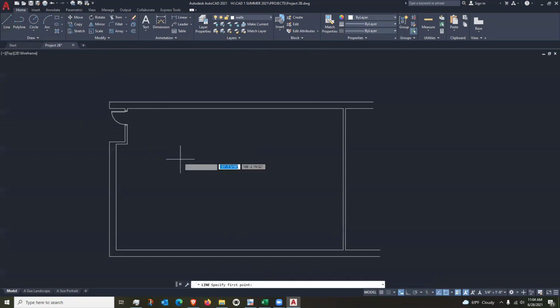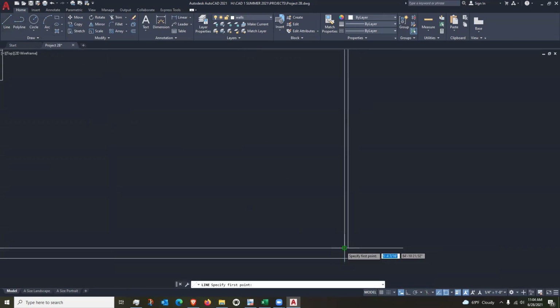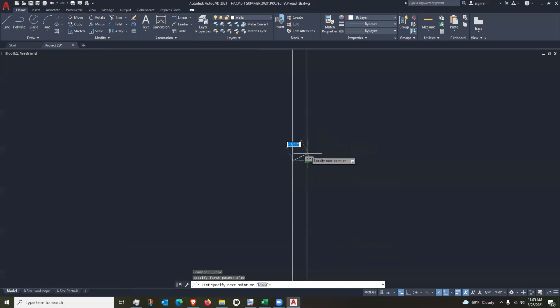I'll go over to the line tool, and go to this intersection, and I'm not going to click. I'm just going to start moving in the direction I want AutoCAD to start measuring. It's sort of like putting a tape measure down here and moving up, and I'm telling AutoCAD to go up 8'10". Enter. Now AutoCAD is going to start drawing that line. I'm going to draw that line perpendicular right there. Hit enter.